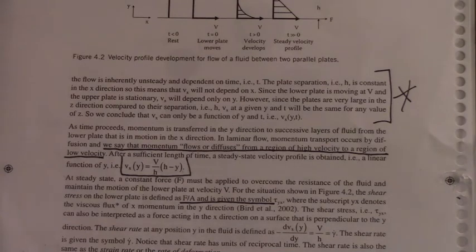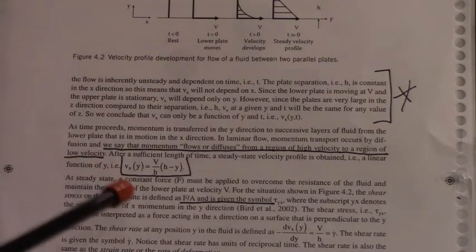And the smart way then to analyze your data, you take that raw data of force and divide it by the surface area of your plate, because in an engineering stress sense, shear stress is a cool variable, and it becomes independent of the size of the system. So you normalize the force by the surface area to take the size of the system out. And that's how we get the shear stress. So F over A is the shear stress.